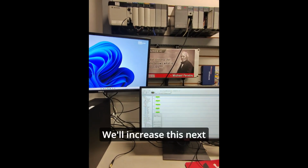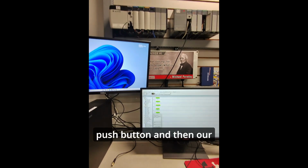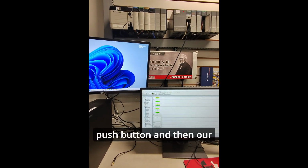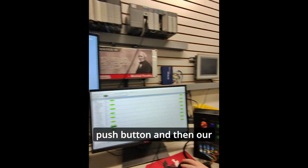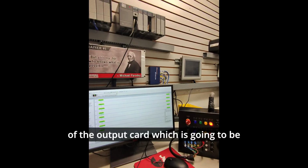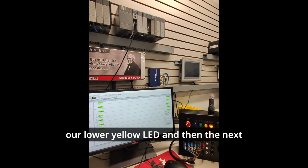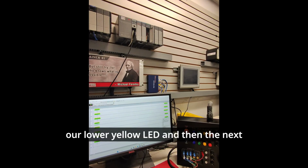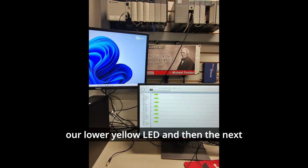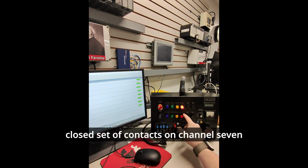We'll increase this next one to channel 6, and this is going to be our lower yellow push button. And then our output will be channel 6 of the output card, which is going to be our lower yellow LED. And then the next one is also a normally closed set of contacts on channel 7.